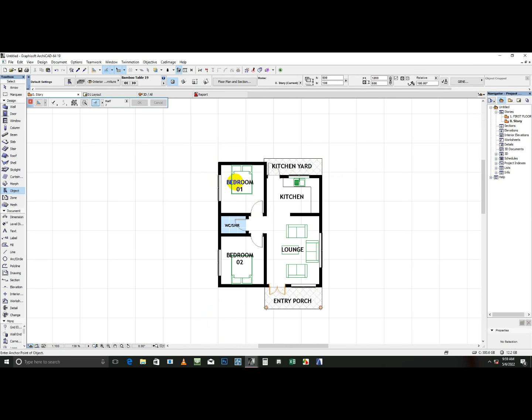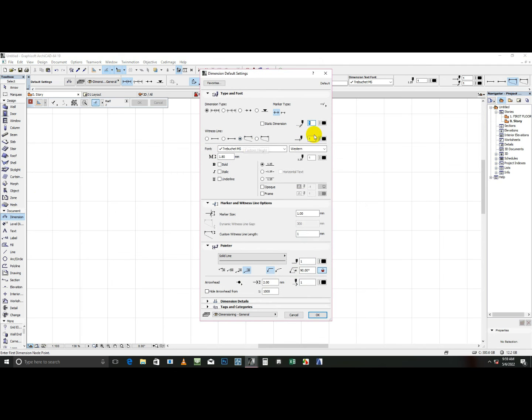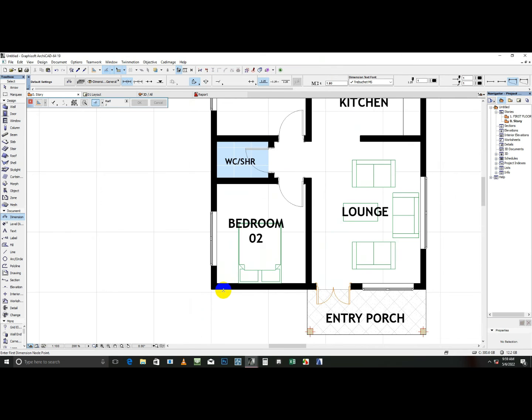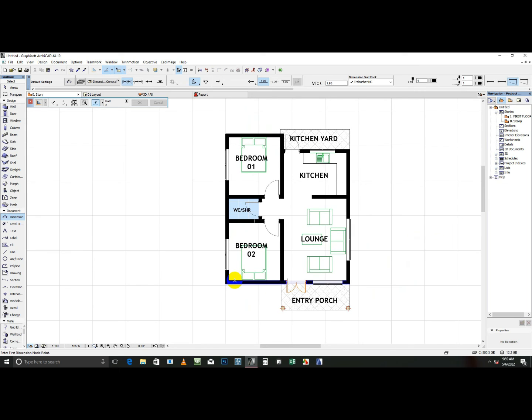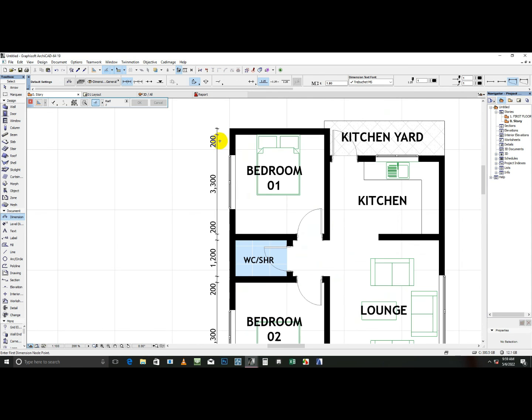So what you're left with is dimensioning. Yeah. So in the dimension from here to here, from here to here. Yeah, generate dimensioning. So you'll come to documents, then dimension. You click on that, set your dimensions the way you want. I guess mine is already set because you remember you used a template that way. So for you to dimension this, you're going to click on that. You click when you get to the line and it gets highlighted like that.